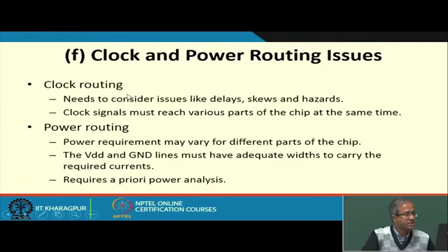So, this is so far as clock is concerned, but for power routing with VDD and ground, this also is a very important problem, because we should not want to mix the power signals along with the normal signals that carry data, because data variations must not couple into the power signals and generate power supply variations. That may not be acceptable. So, usually the power signals, the VDD and ground, run on separate dedicated metal layers. So, interference and crosstalk are minimum there.